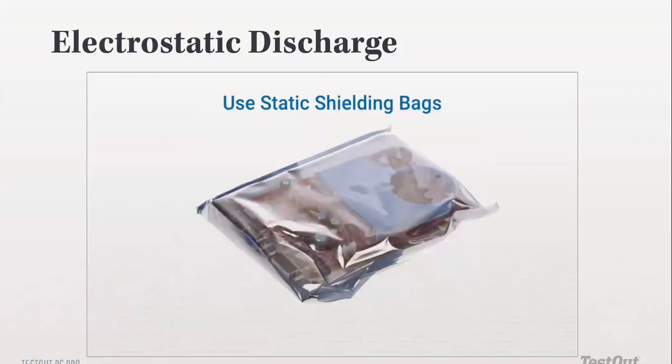Now, you'll find yourself having to store some spare parts, working spare parts, so that if you have an issue, you can use that working spare part to troubleshoot and find out if it is the component currently in the PC which is faulty, or if it is just that the connector itself is not working. So in order to store these spare parts, something like a RAM or a graphics card, you put it inside a static shielding bag. It is a bag that prevents buildup of static electricity.